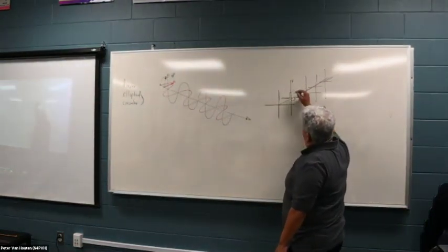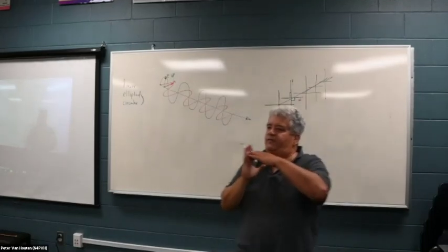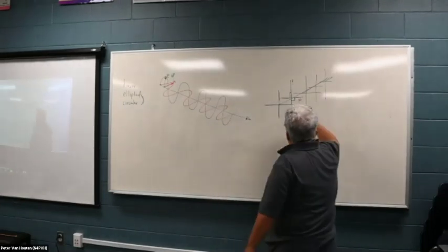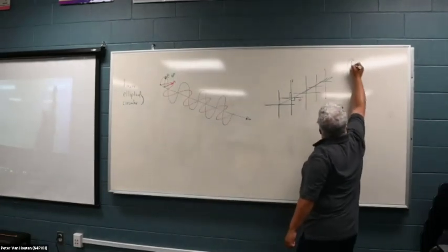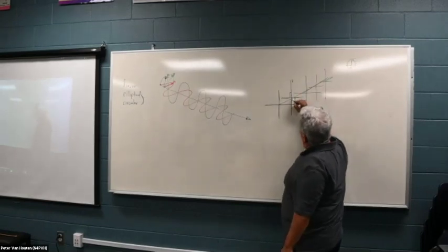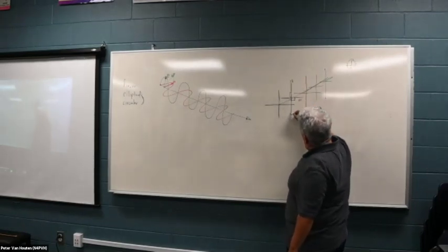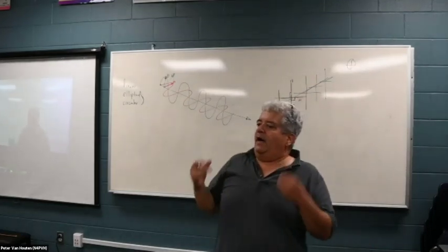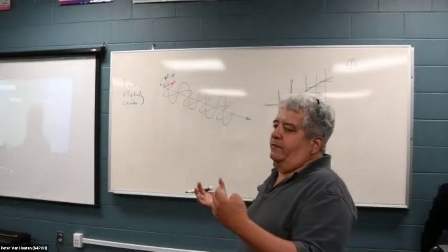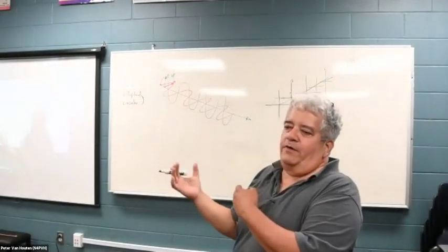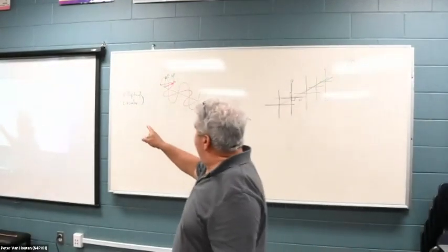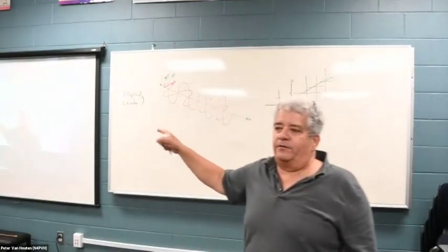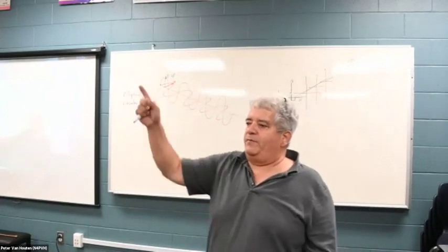Then if they are physically at the same distance to the target, meaning that relative to the target, which is here, my antennas, both the vertical and the horizontal, have the same distance, then how can I put this, that one is a quarter wave behind the other, just to get the effect that we got there on the video, that it became circular?